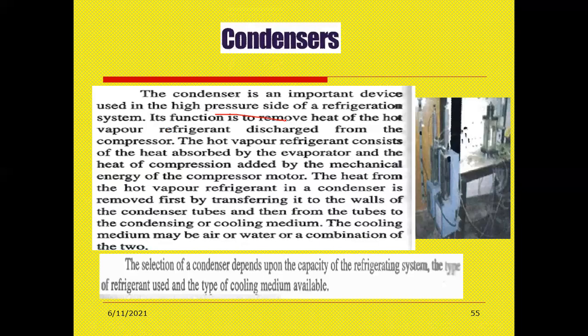The function is to remove the heat from the hot vapor refrigerant discharged from the compressor. The hot, high pressure vapor coming from the compressor has its heat removed. The hot vapor refrigerant consists of heat absorbed by the evaporator and the heat of compression added by the mechanical energy. The mechanical energy is supplied by the motor.